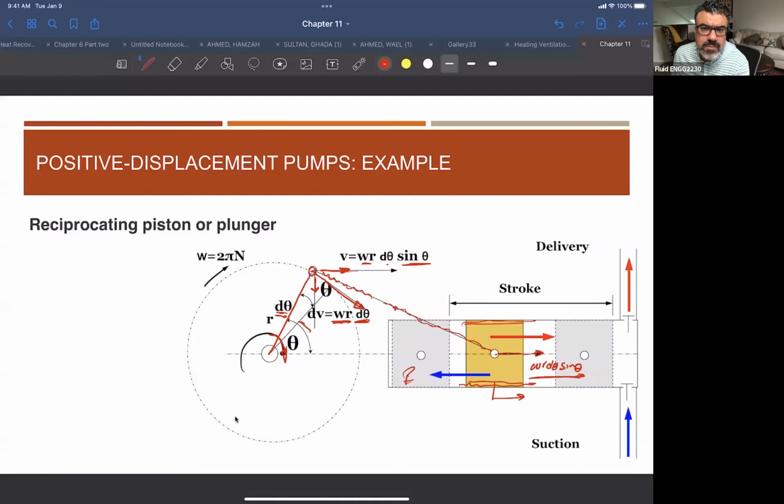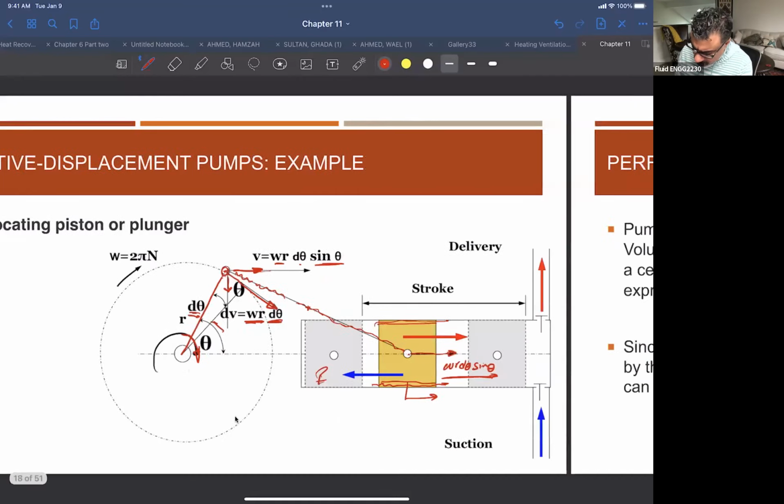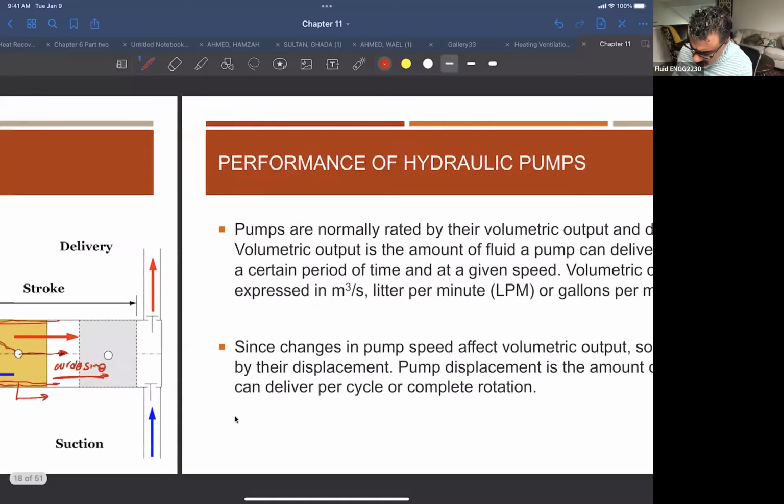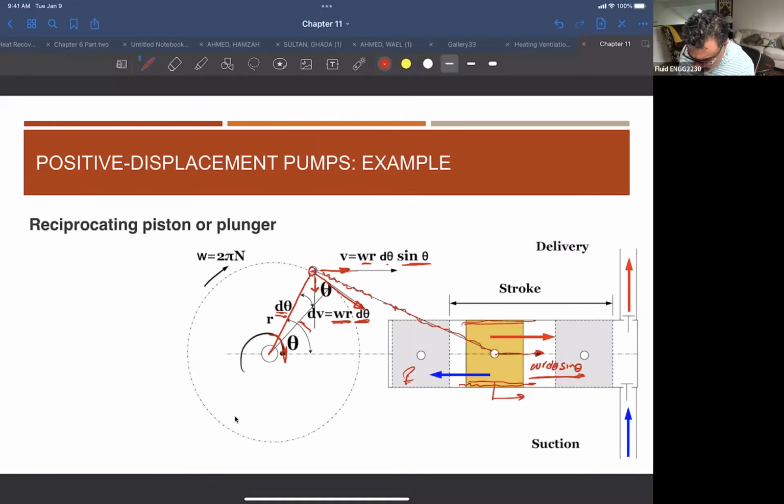And now we have to consider some new terminology called volumetric efficiency. The volumetric efficiency is basically what the pump is actually delivering, divided by the theoretical flow rate based on the simple design of this pump. So if you know the amount of leakage, if you know that there is 3% internal leakage inside the pump, that means the volumetric efficiency is 97%. Okay. So displaced volume means, you see here, this is the volume that you are displacing here.